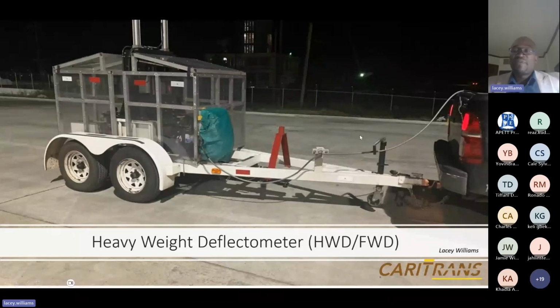So the heavyweight deflectometer, as I described, is an impulse type piece of equipment. I don't know if you can see it clearly from your end, but we have a load stack similar to weights in a gym, where you can select the loads depending on the strength of the pavement or other known factors. You have the masts with pistons that you drop on a load cell, and there's a rail that you set on the ground. Once you have the vibrations, depending on the stiffness or the thickness of the layers, it causes a certain response, which is then recorded in the CPU and transferred into the computer, which is connected by the data cable.